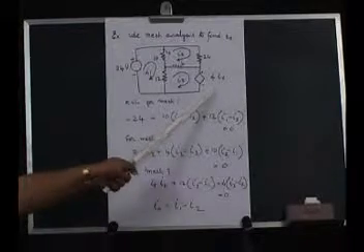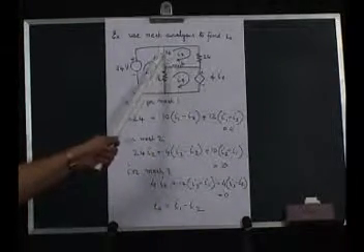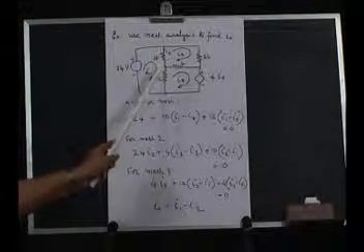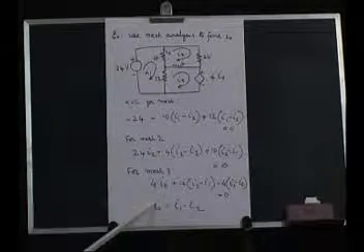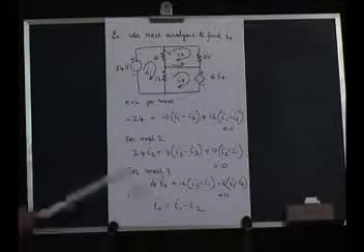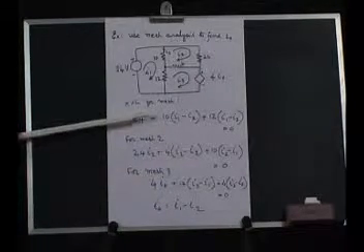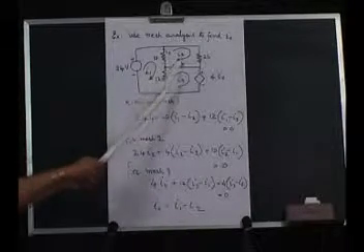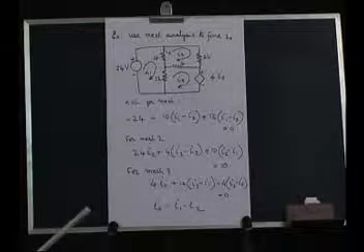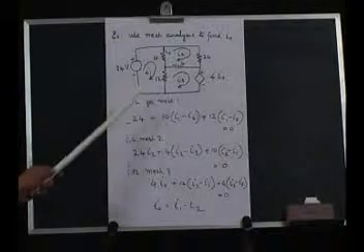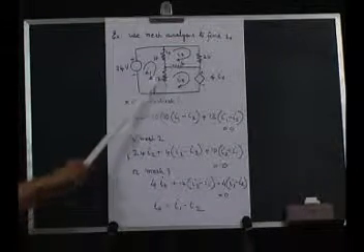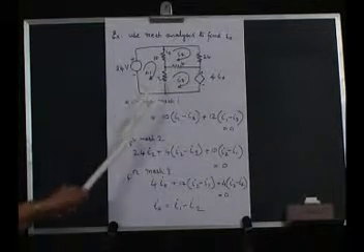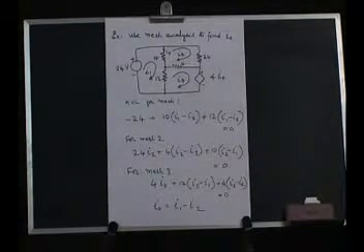What about I0? I0 is the current flowing here. How much is the current flowing? The current I1 is flowing in the same direction as I0. Current I2 is flowing opposite to that one. Therefore, I0 equals I1 minus I2. So we have a sufficient number of equations. If we simultaneously solve these equations, then we have the current solutions for I1, I2 and I3, and other voltages, branch voltages, etc., we can find out with Ohm's law like this. For instance, the drop across this is 12 into (I1 minus I3). So that is the drop here. So we found out the solution for this particular problem.